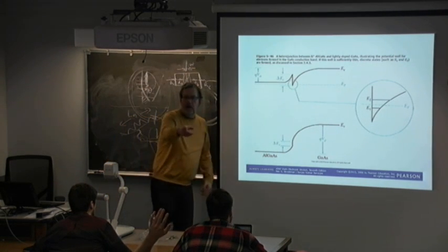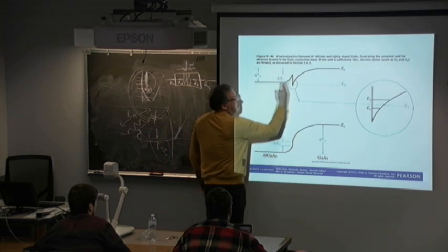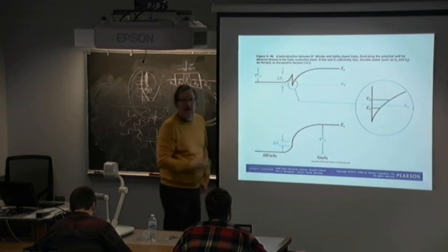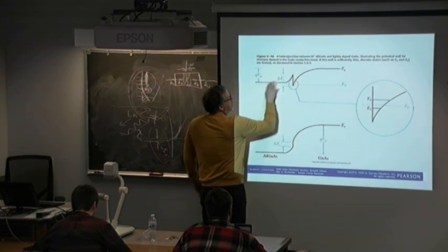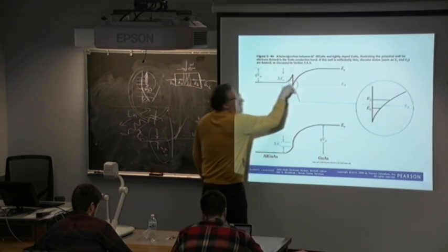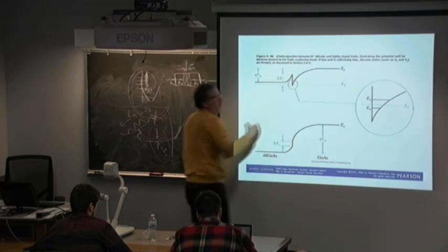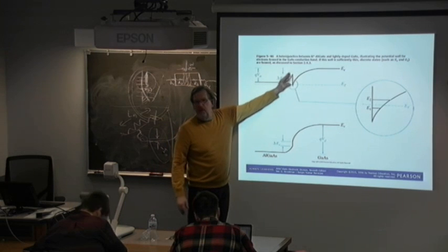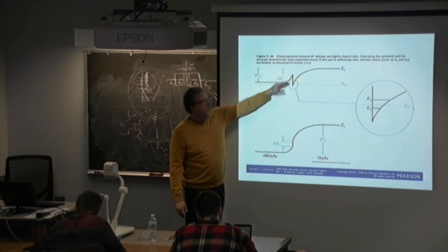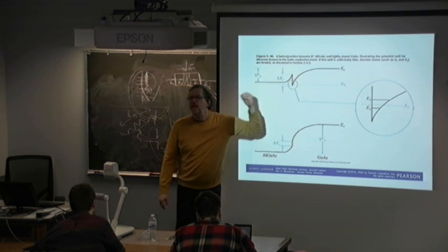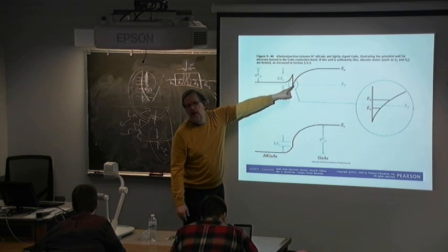And then the last thing is the ionized impurity scattering is minimal because the dopants are here and they modulation dope, they basically transfer. The electrons are bouncing around through kT kinetic energy, and they're trying to find the global minimum. Where's the global minimum? Right here.